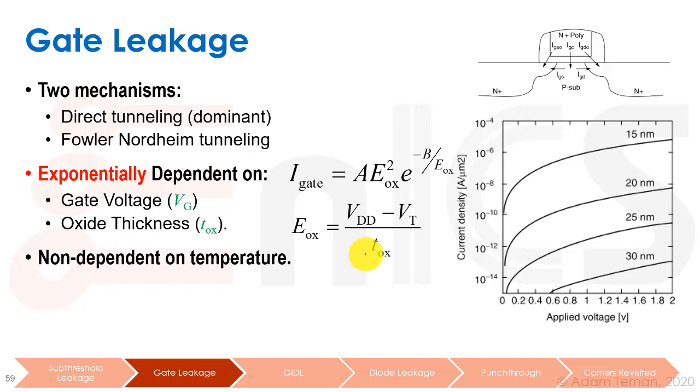Again, what I told you before is that our main gate leakage goes to whatever is under the gate, if it's going to be the substrate when there's no channel, or the channel, which will then probably be divided between the source and the drain if there is a channel. There are also some direct components of the gate leakage which go directly to the source or directly to the drain in the areas of overlap between them.